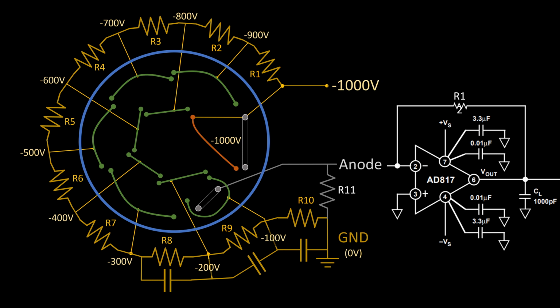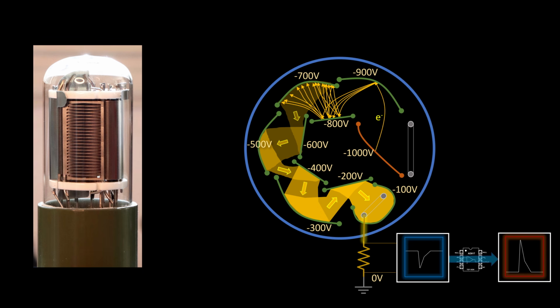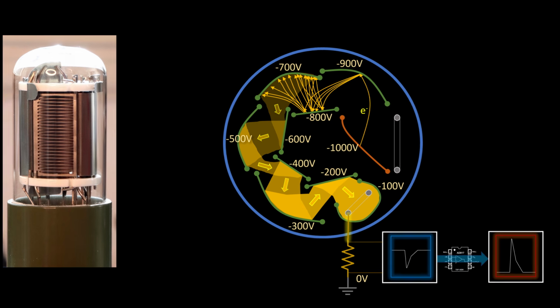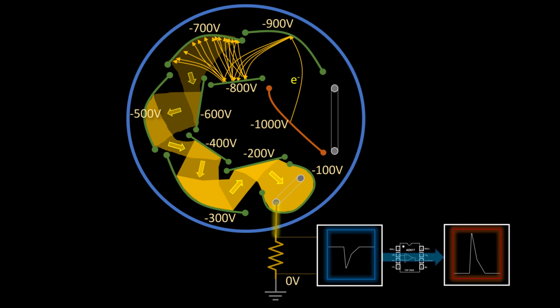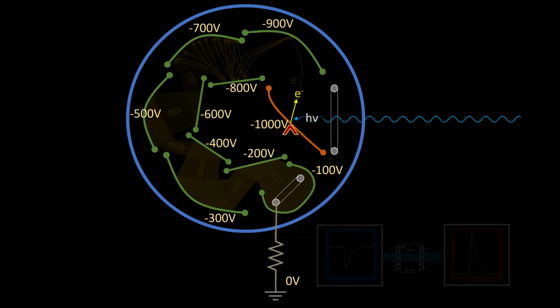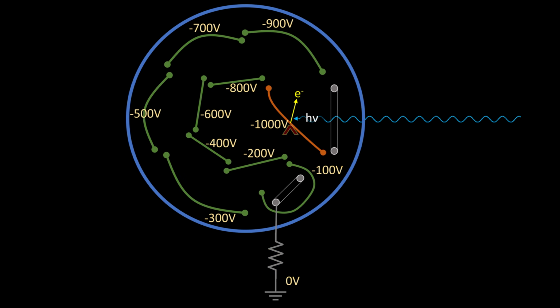But the latter value does of course not include the limitations imposed by the anode grounding resistance and the amplification electronics. So this is what single photon detections actually look like. We measure a short current pulse, which is the result of an avalanche of electrons initiated by the irreversible and quantized transfer of radiative energy upon a single electron.